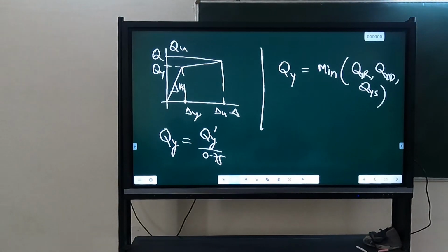So if we assume the strain of masonry and concrete, then we have considered compressive force, that is, when in tension, there is no tension. There is nothing to take tension. Masonry cannot take tension and there is no reinforcement. So can it take moment? No, you should not say that after doing rule number 1.